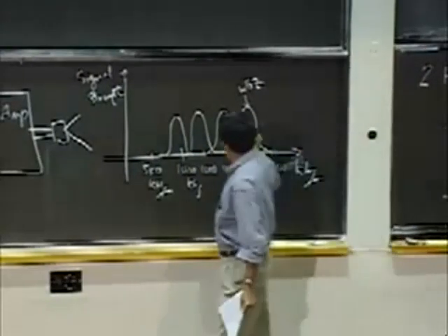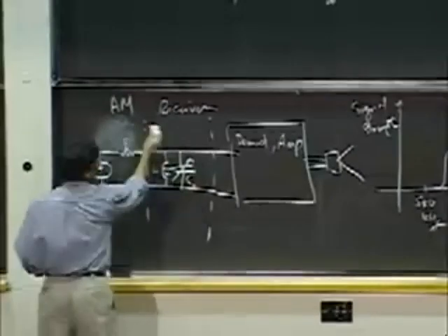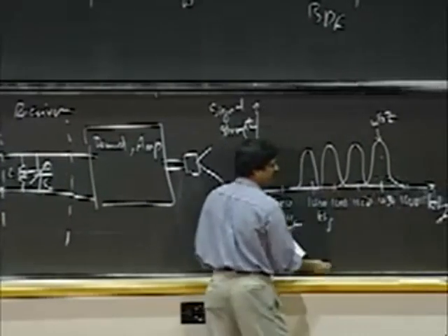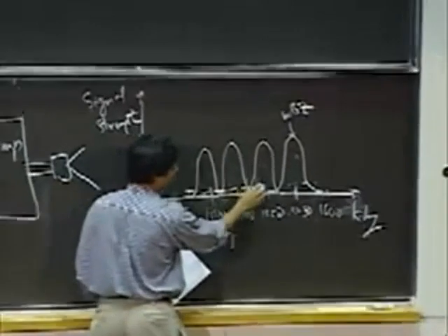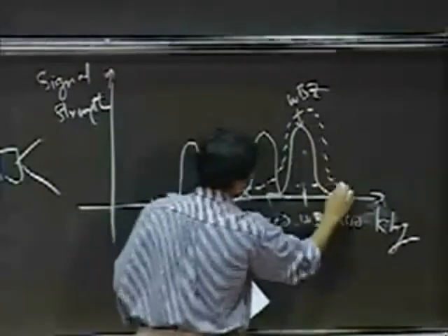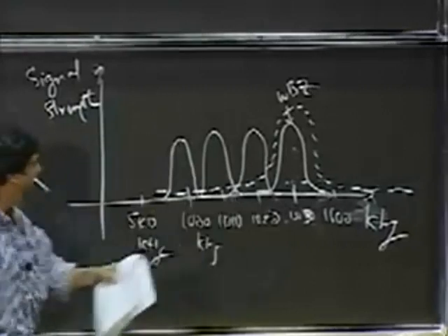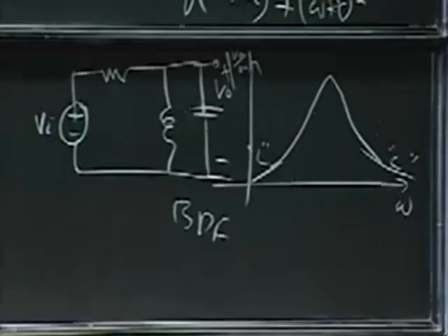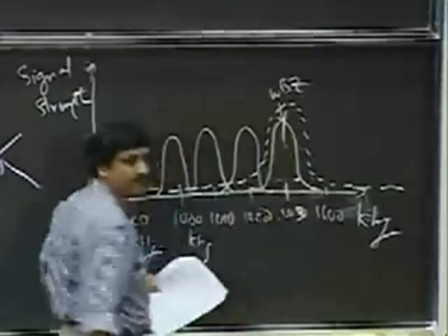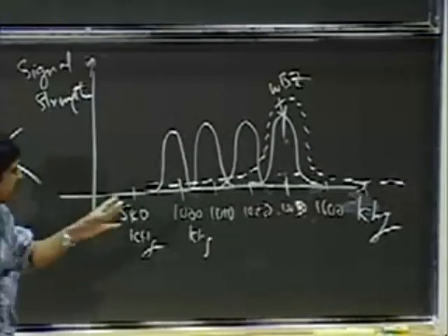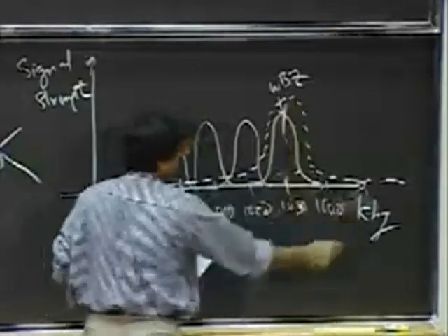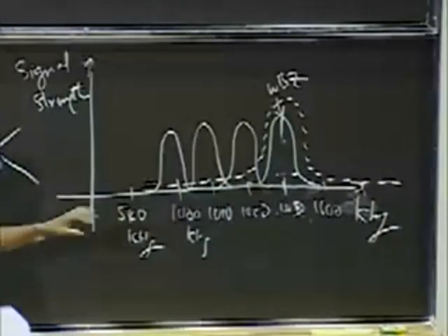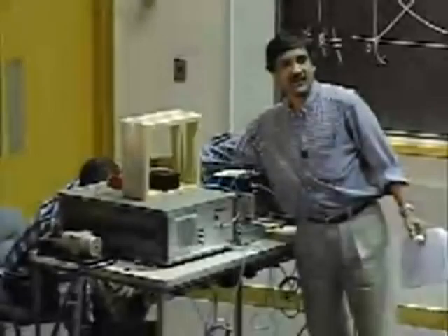Okay? So how do you listen to that station? The way you listen to that station is you put a filter here. You put a filter that does the following. Let's say I want to hear WBZ 1030. If I pass this entire signal through that filter, and if I arrange to have the omega naught of my filter at 1030, then this is the response of my filter, and I'm going to pick out this guy and cut out everything else. Okay, I'm just going to get this. And that is...